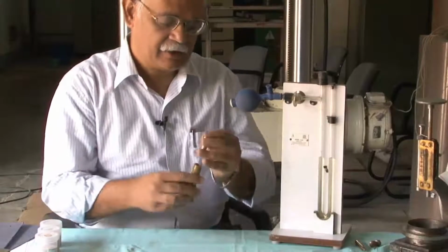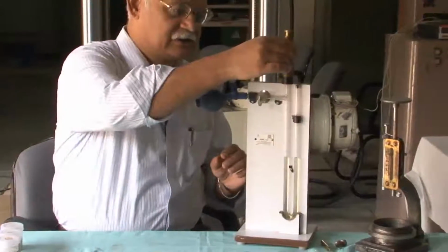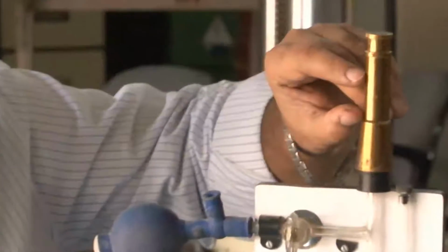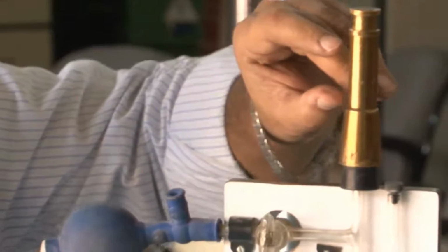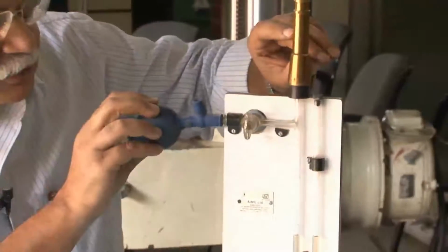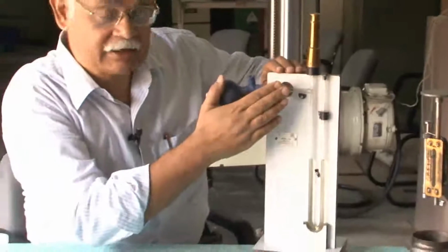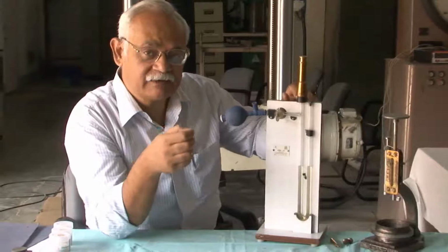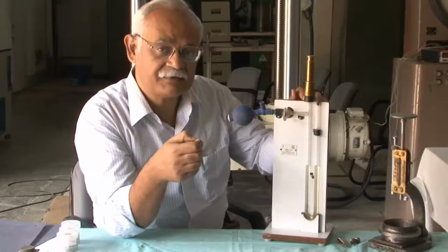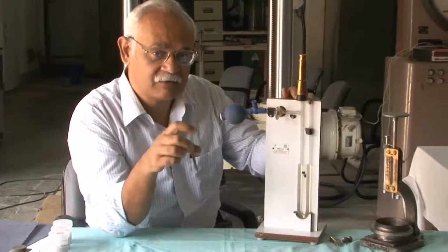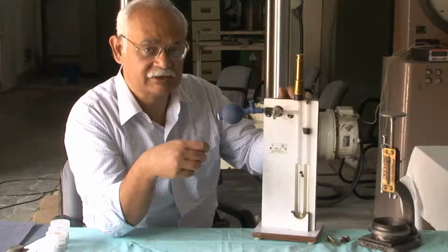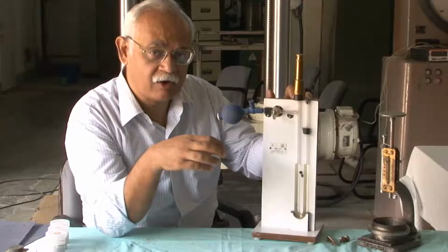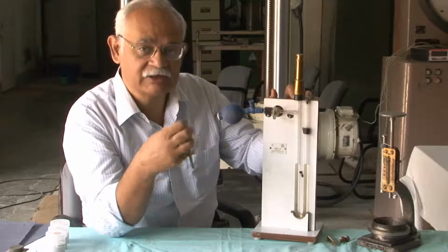manner, close this, put this on this surface here, and then the cement sample which is packed in this part as a bed, we allow a certain amount of air using this contraption here to pass through that bed. And if the cement is very fine, then the amount of time it takes for a certain amount of air to pass through is much larger. So, we calibrate this apparatus using a powder of known fineness, and we know how much time it takes.